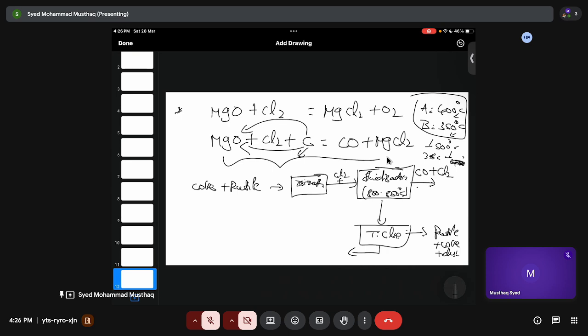When you do that, the FeCl3 will come out, because I have said before, whenever you are trying to do the extraction of titanium, you have iron with it. So you need to remove iron first. And when you do the scrubbing, you add your liquid. Now what I am trying to do is add liquid TiCl4, titanium tetrachloride. So we add this, and we do the scrubbing.